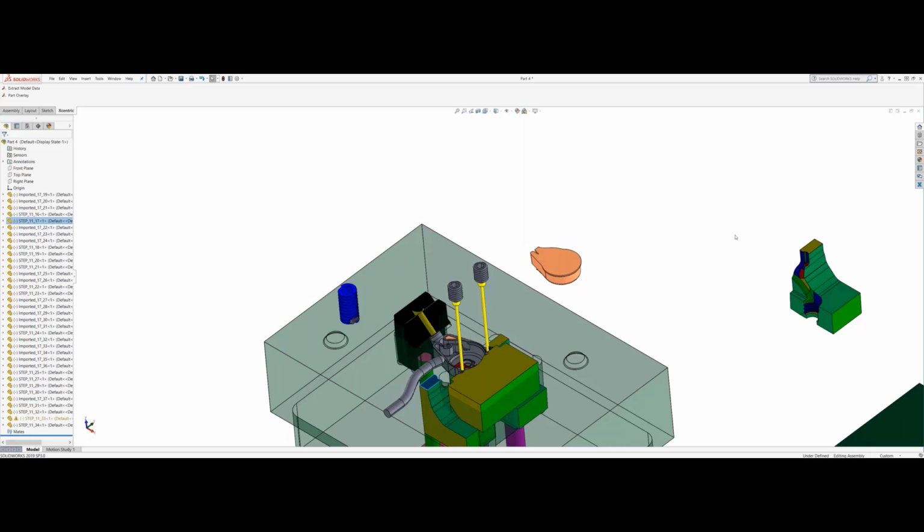John, question that builds off of that last one. Do you help the customer break down the manual tool option and the automated tool option concerning tooling and part costs? Yes, we can definitely do that, and that's really going to be driven by the customer and the quantities. Manual tool, cheaper, manual parts more expensive, and it's flip-flopped with an automated tool. Your automated tool is going to be a little more upfront cost, but your piece price is going to be much lower. So if you know you're going to be running 2,500, 5,000 parts, moving to the automated tool up front is going to pay for itself in pretty much no time.